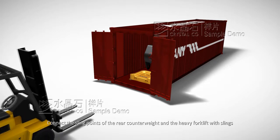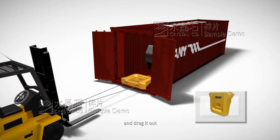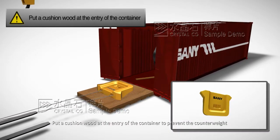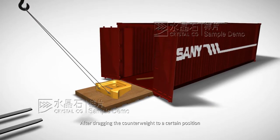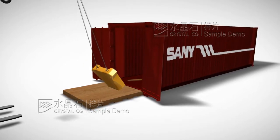Connect the sling points of the rear counterweight and the heavy forklift with slings, and drag it out. Put a cushion wood at the entry of the container to prevent the counterweight from falling suddenly. After dragging the counterweight to a certain position, lift and move it with a crane to a proper place for mounting later.